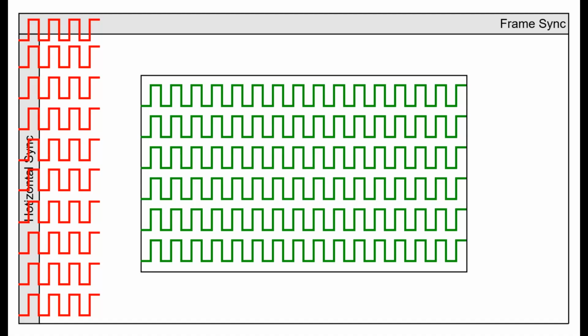A 32K chip can still operate on 7-bit row, but a 64K chip needs 8 bits for both. Some manufacturers deliberately made their chips 7-bit compatible, and this is great for upgrades and mandatory for an original Dragon 32. The later versions of the SAM, 74LS785, actually fixes this and uses an 8-bit counter, but also pushes the refresh timing past the 2 millisecond maximum for a 4116.